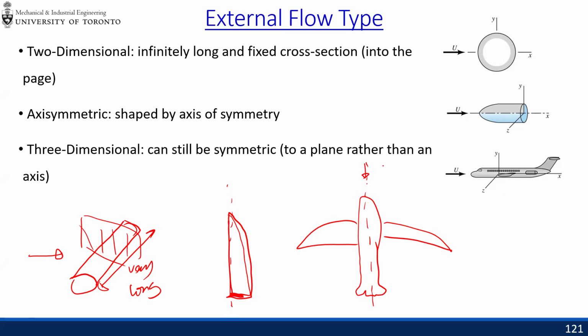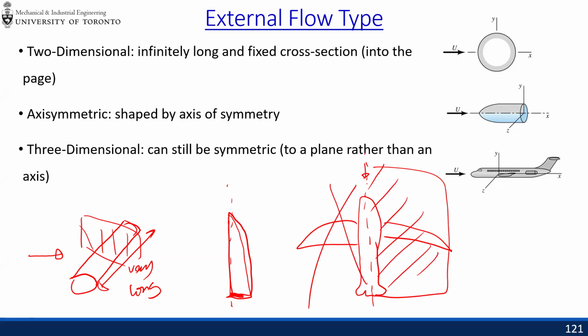Rather than simulating the whole thing, we just want the right half. The left half, we can just skip, and imagine putting a mirror down the middle. That saves you 50% of the computational cost. It might not sound like much, but when your case is, say, 100 core years, saving 50 years is quite significant.